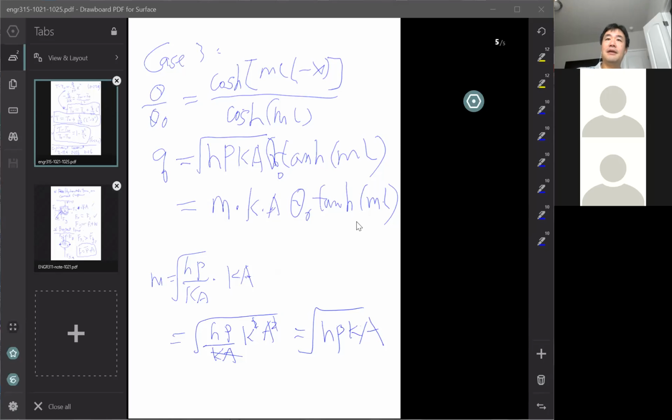And if case two, convection condition at the end on the tip, is long, then the temperature difference is small. Then the convection through the tip is negligible. Then case two becomes case three. Okay, so that will be better. Okay, good. So these are the three cases.